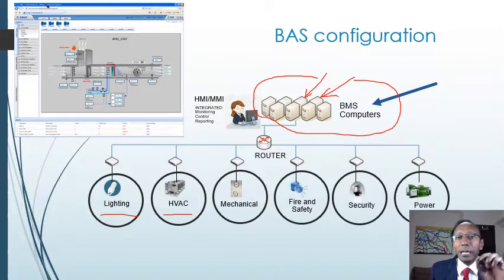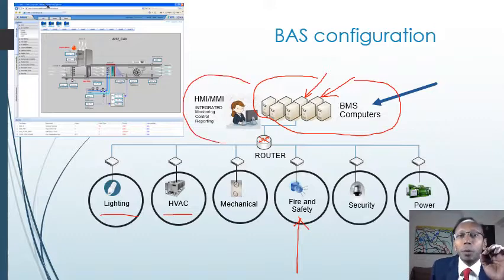So the FCC room is the place where all the BMS related subsystem computers are located, and that's a place where, as a mandatory requirement, there is a human being 24 hours, 365 days. So since FCC has this requirement that the room should be manned, why not use that facility for controlling other facilities? So typically this is the place where a man-machine interface or human-machine interface to control the entire building automation system is located. Now let us explain to you what is inside an MMI.